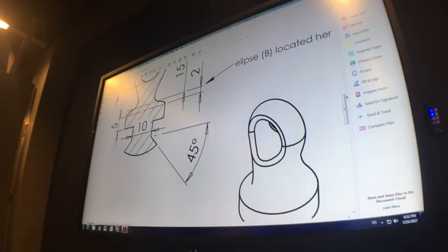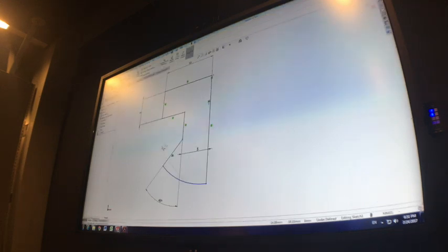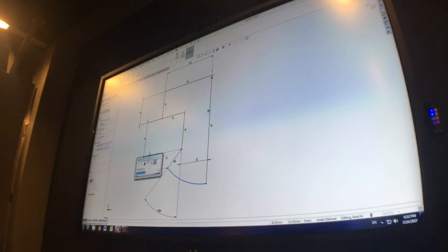The other, I need to give that line dimension. Again, that looks pretty close to a 5 or 6. Might go 6 for that one. And then this last one, even though the line's on an angle, I can dimension it coming straight out, or I can move my cursor to a horizontal position. It'll give a sort of horizontal position between the two endpoints, or a vertical dimension between those endpoints. I might just go with 3.